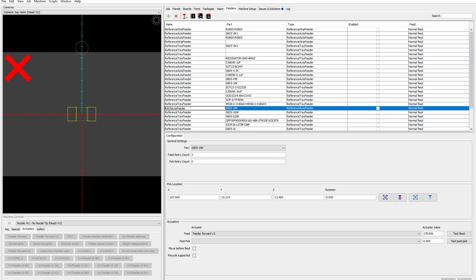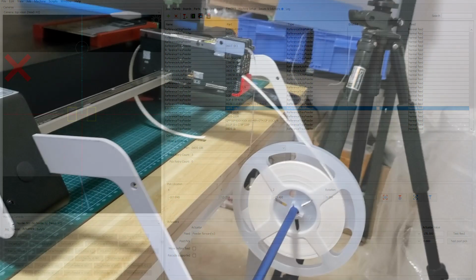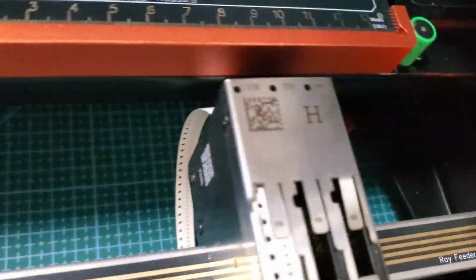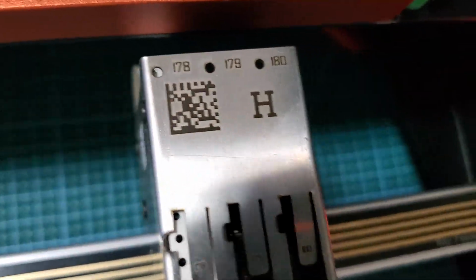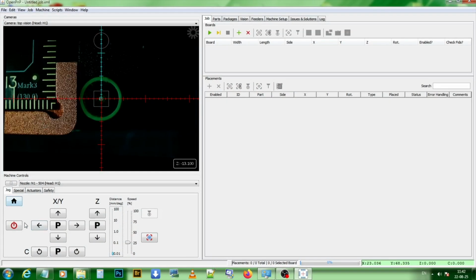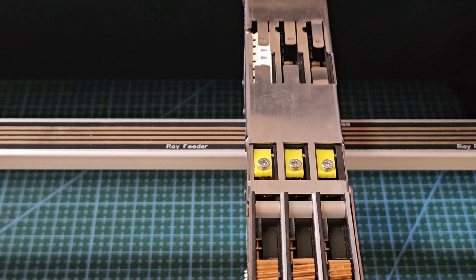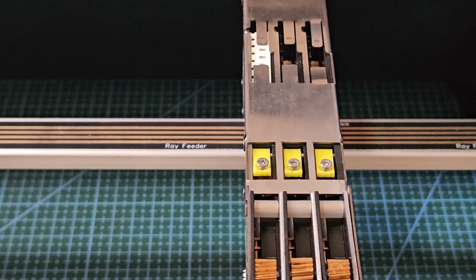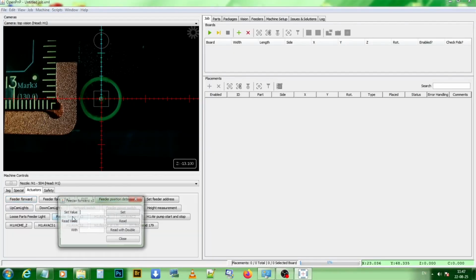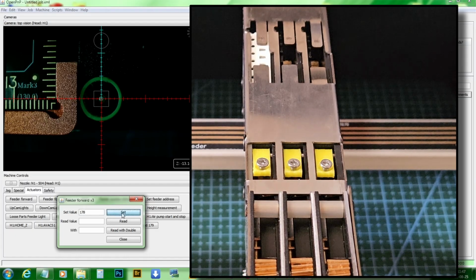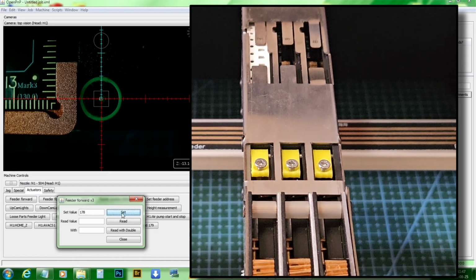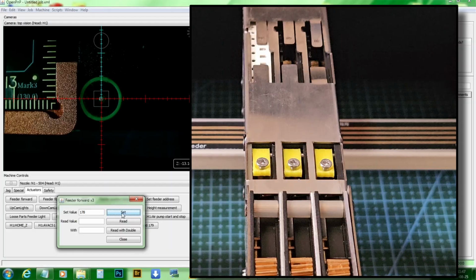For now, we simply test if the actuator works. So we go in the actuator panel and we test the feeder forward. It has 1 4mm step of increment. And then we test the feeder forward by 3. This has 3 4mm steps of increment. And more 3 steps. And it works perfectly.